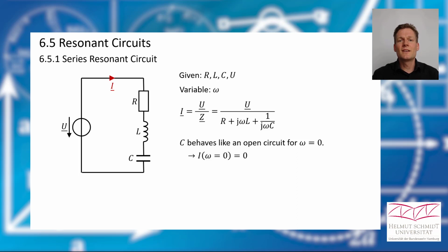Okay, and now let's increase the frequency. And if we do so for very high frequencies, the inductor behaves like an open circuit. And that means for very high frequencies, again, our current will become 0.